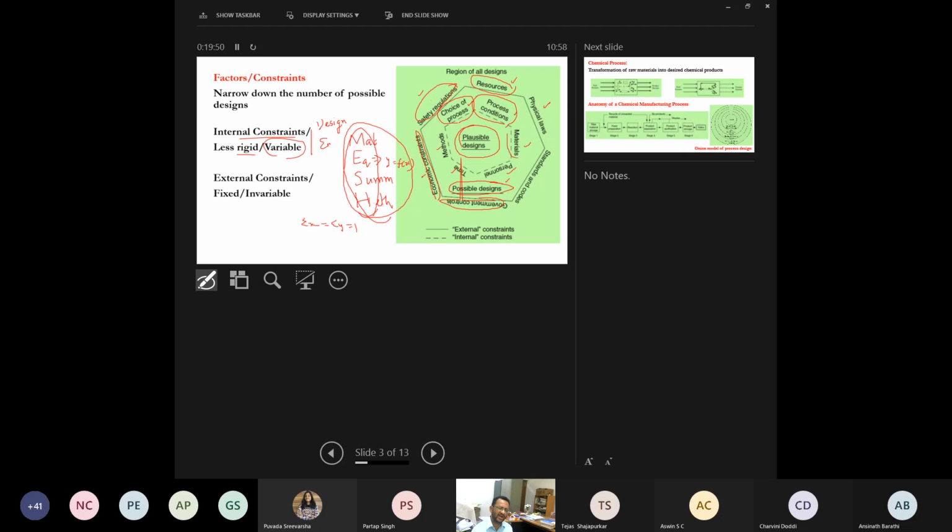Okay, so the materials again matter, whether it is a heat exchanger, and which fluids would be taken in which side, shell side or tube side. This is based on the type of materials, or whether it is corrosive in nature or fouling in nature. Okay, whether it is reactive. So we have to see so many things. After seeing these materials, you can select whether it is a copper tube or an alloy tube or aluminum tube, or a mild steel, so many things.